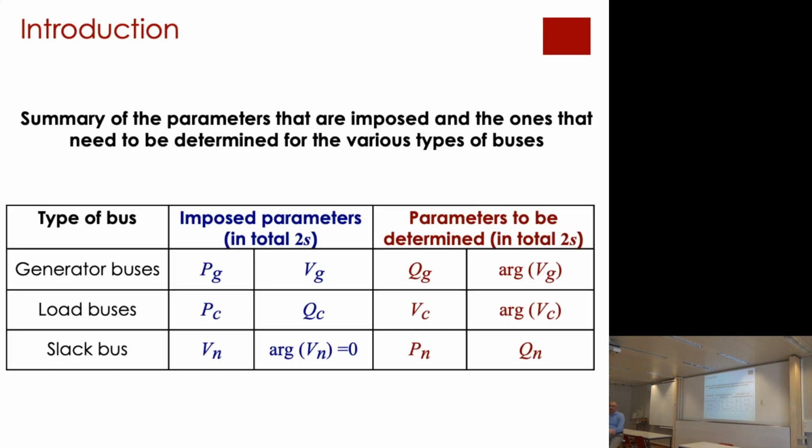Normally, all the equipment of a power grid is rated for a specific value of voltage. This means that a given piece of equipment, a breaker, a line, a motor, even your laptop when you connect it to the power plug, is rated for a specific value of voltage. The insulation in the equipment is designed to withstand a given amount of voltage. You cannot go below or above this voltage. Typically, the bandwidth within which the voltage can move is plus minus 10%, just to give you a very rough number.